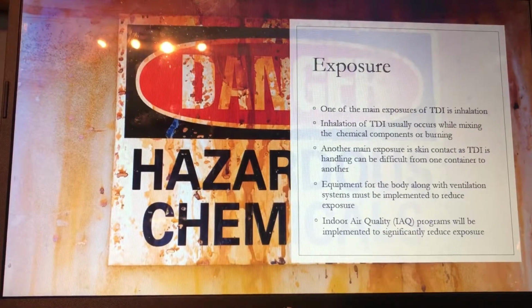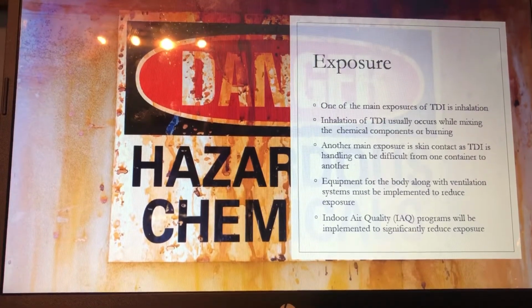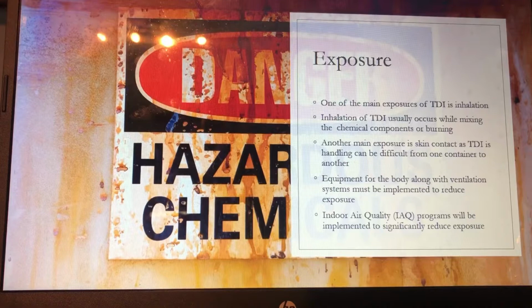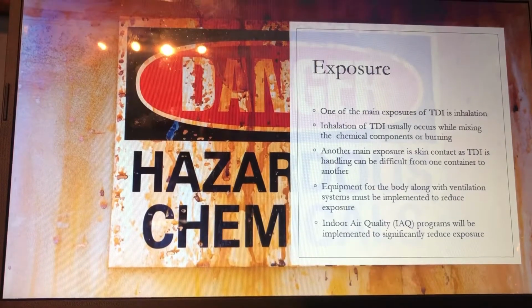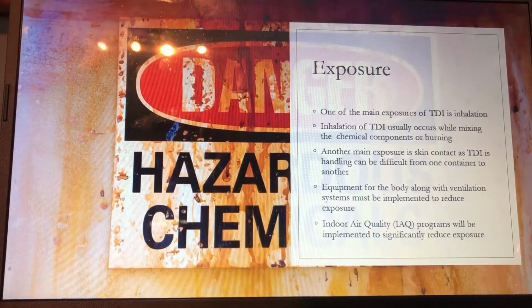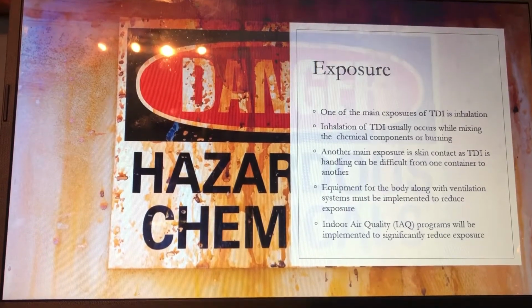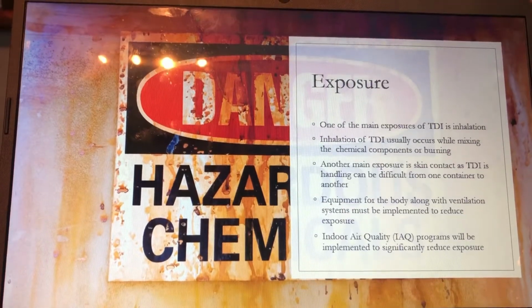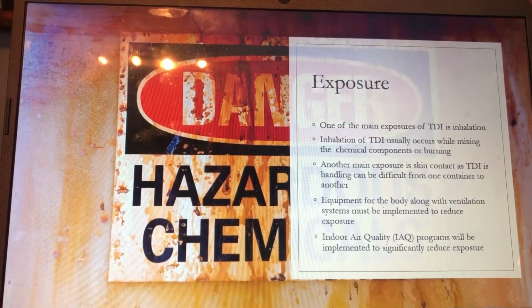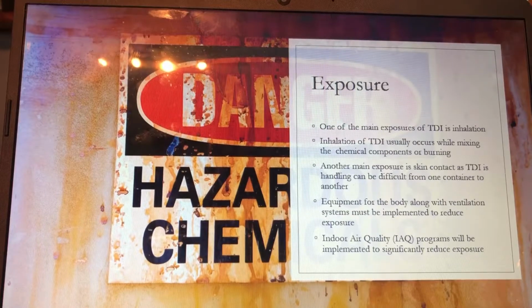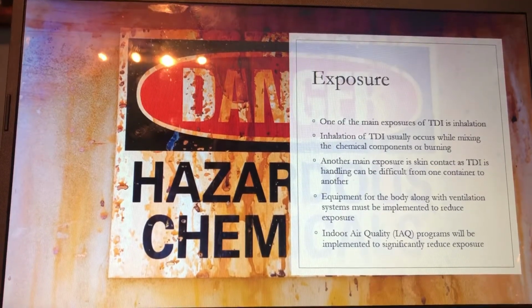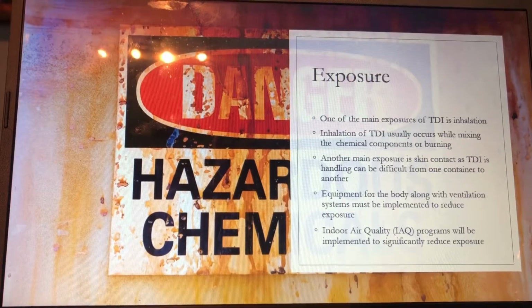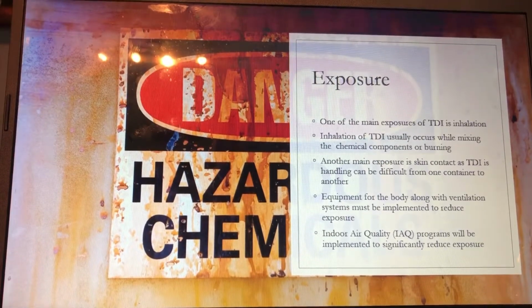One of the main exposures of TDI is inhalation. Inhalation of TDI usually occurs while mixing the chemical components or burning. Another main exposure is skin contact, as TDI handling can be difficult from one container to another. Equipment for the body along with ventilation systems must be implemented to reduce exposure. Indoor air quality, or IAQ, programs will be implemented to significantly reduce exposure.